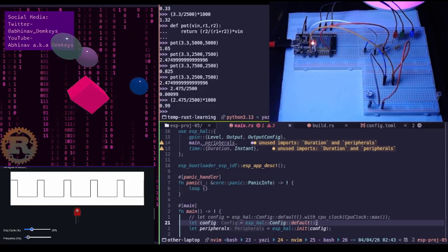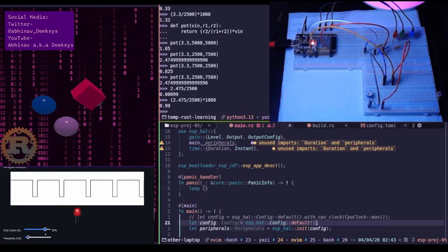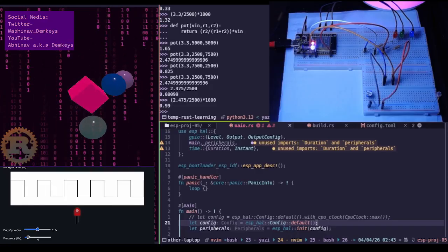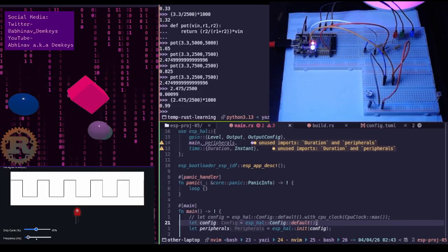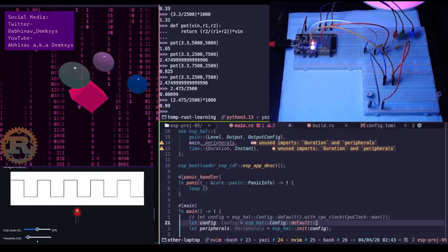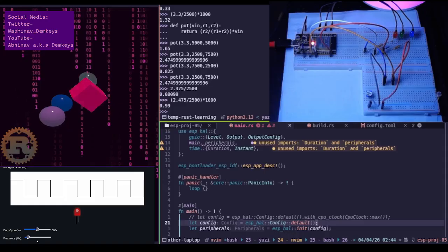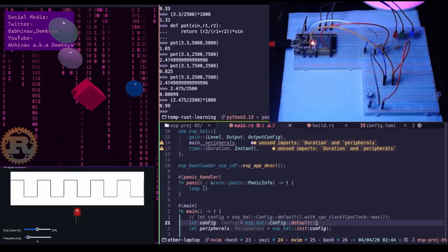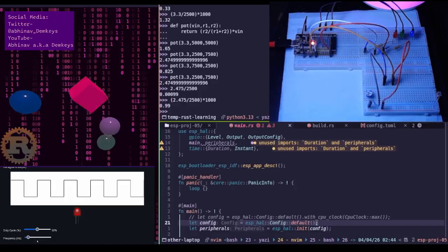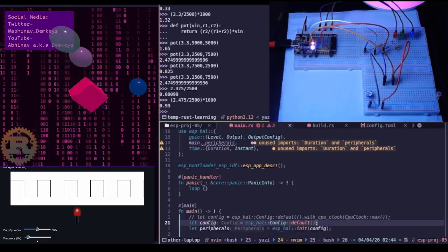And this duty cycle is how long it remains on throughout that one cycle. So the combination of duty cycle and frequency creates the illusion of the LED being dim or bright. And that's kind of interesting. With PWM, we are essentially taking advantage of the limitation of the human eye.